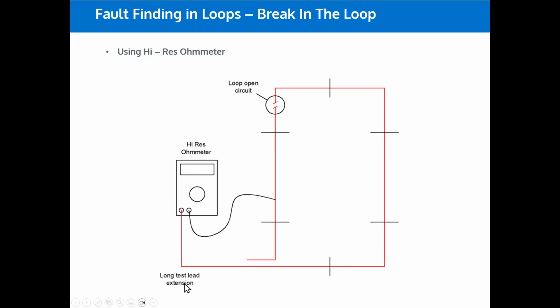You've got your long test lead extension here, and what you want to do is check at various points along the route until you eventually get a short circuit.